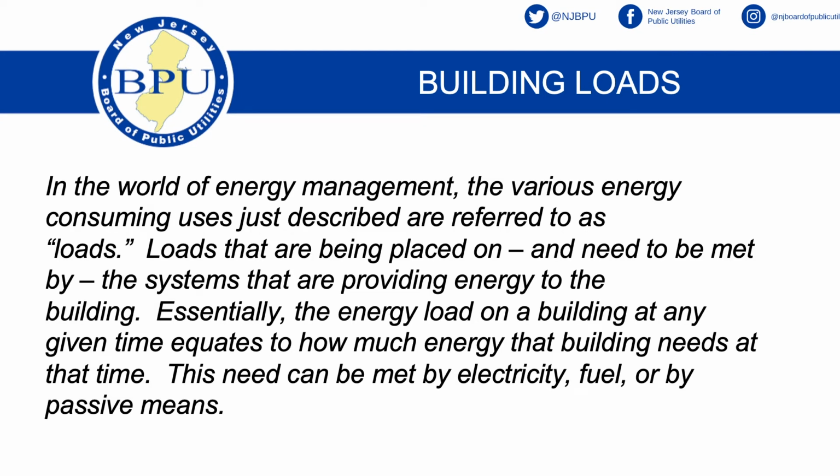So it is time dependent, the load profile. It goes up and down pretty much every day in the building. Usually the weekdays are a little different than the weekends. And then there are seasonal things. The loads go up and down. In the summer, your electrical load should go up and the cooling load should go up. But the heating load should go down.